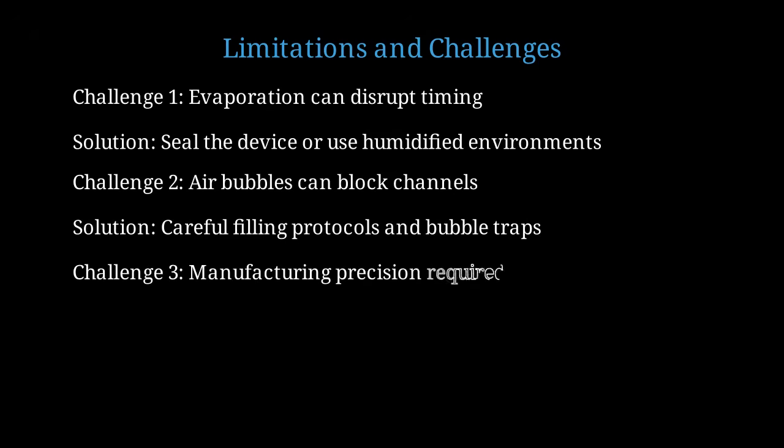Third, manufacturing precision is critical. A channel that's supposed to be 50 micrometers but is actually 55 micrometers will have a 10% difference in capillary pressure, which can break the logic sequence.